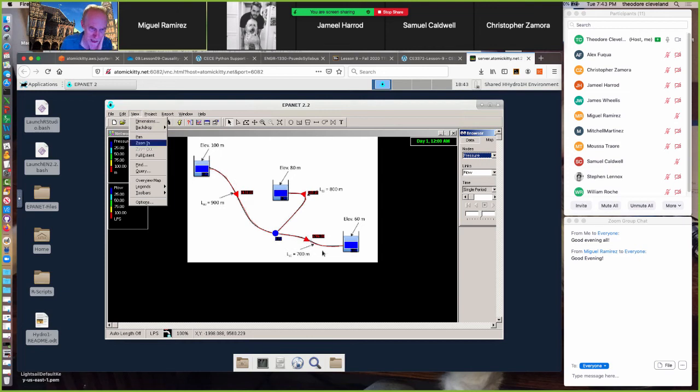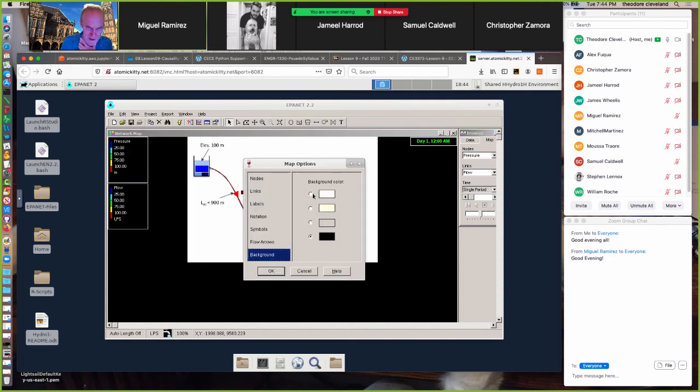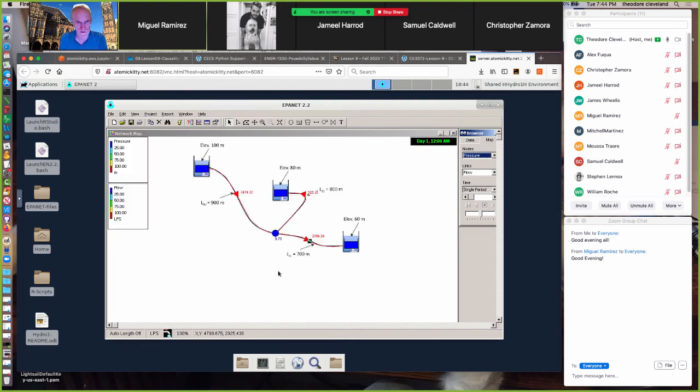When we're in the SI units, the pressures it reports are in meters of water. And so an analyst has to know how to convert with that. It's a shame it doesn't report it in kilopascals or something meaningful, but that's okay. It still did the hydraulic calculations for us. So there's the example there. So let me go ahead and save it.